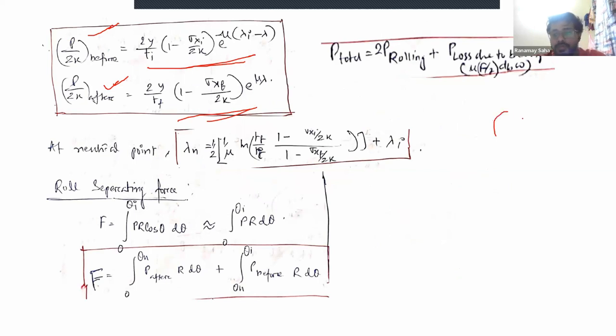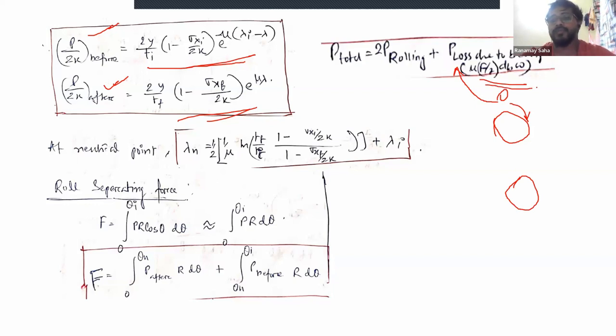which are supporting the rolls. Okay? If you don't know the rolls, these are rolling, right? So there should be some bearings over which these are rolling to avoid the friction, right? So these bearings can also offer some frictional loss. And to account for that, we generally take the frictional loss as friction coefficient mu multiplied by F by 2 into dB, that is the diameter of the bearing, into width,